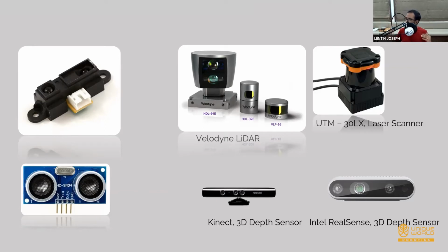But robots also need two cameras for perceiving 3D information. Otherwise, if there is no stereo camera, we can use a depth camera as well to perceive the depth of the environment. It actually works with a different technology using IR, time-of-flight technology. It projects some IR light into the environment, then collects the reflection, then computes the depth.